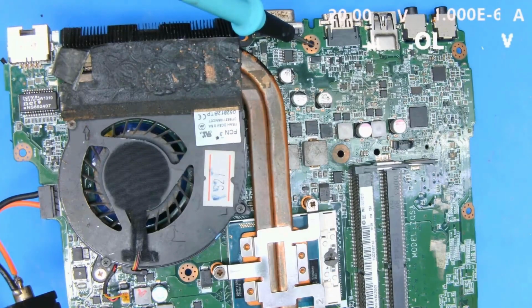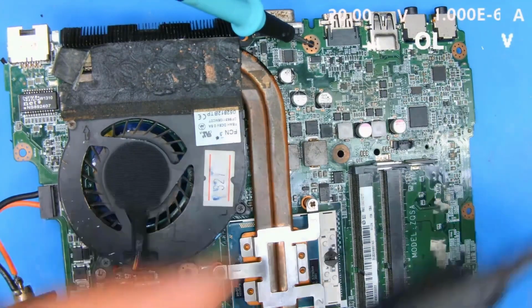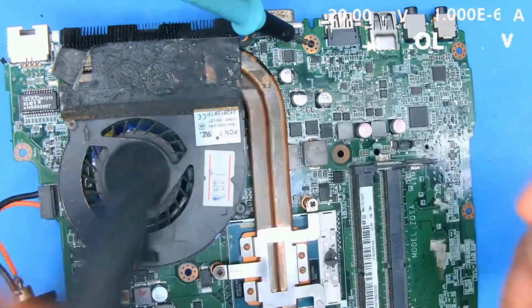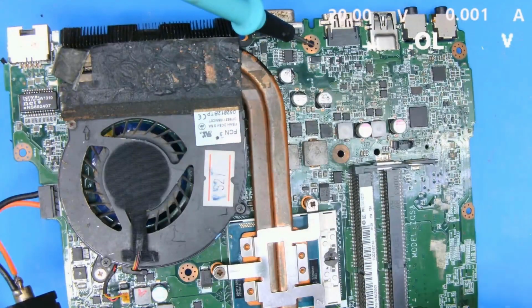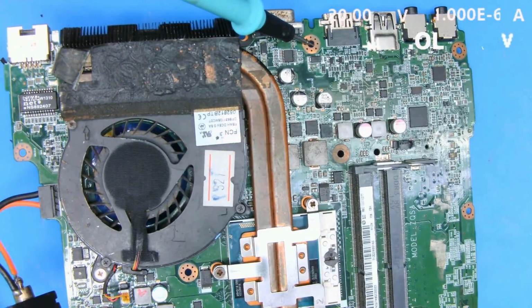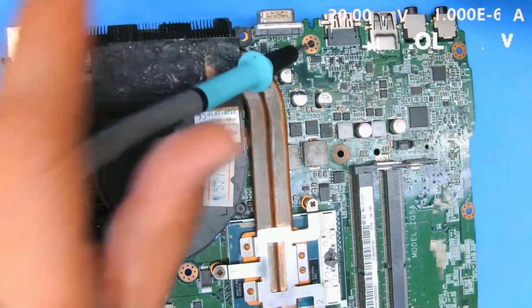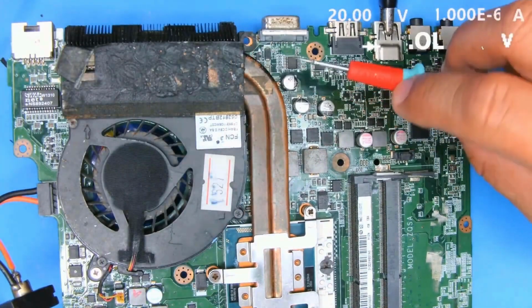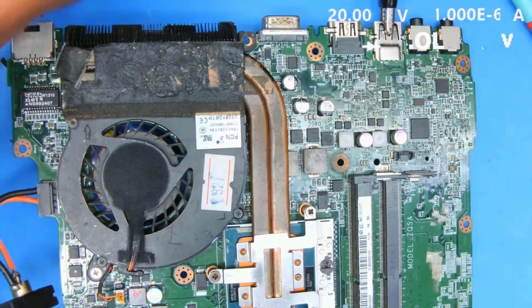It's simple. We need to use this and then use alligator clips like these, connected from the power supply. The red and black clips are connected directly from the power supply. Then inject power at pin 49 on both sides to determine which side is positive and which is negative. Use the black clip onto the ground right into the slot, okay? We don't need to use the meter. Just use the tip of the needle to insert and inject the power.